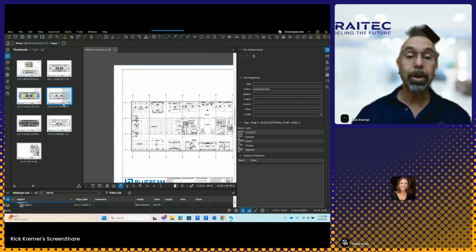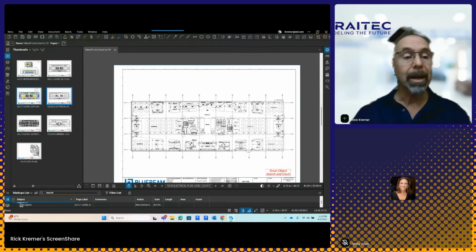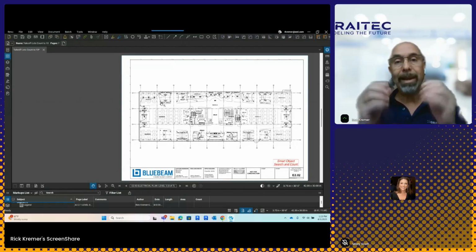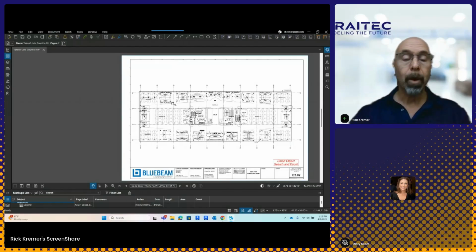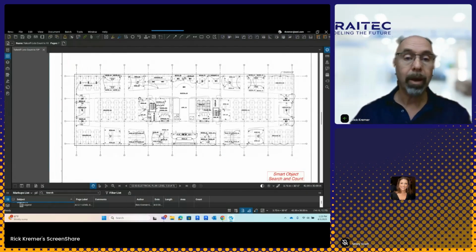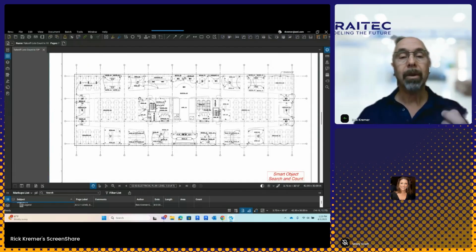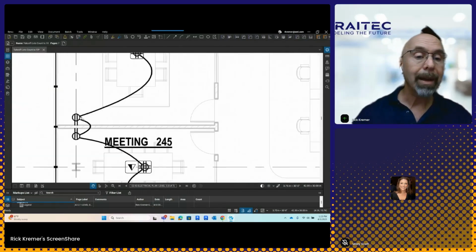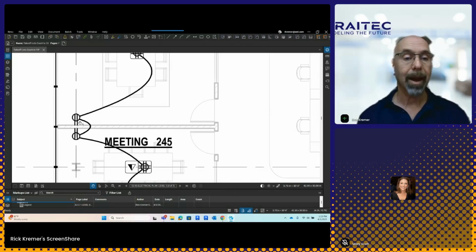Next, let's start to take a look at different things that we can do. In this case, we looked at creating areas, but what if you say, Rick, we need to count objects? Over here, I'm going to count what I call widgets, anything that you want to count. So let's say we're counting P&ID or electrical outlets or anything of that matter. And in this case, I want to go through and count how many duplexes I have.